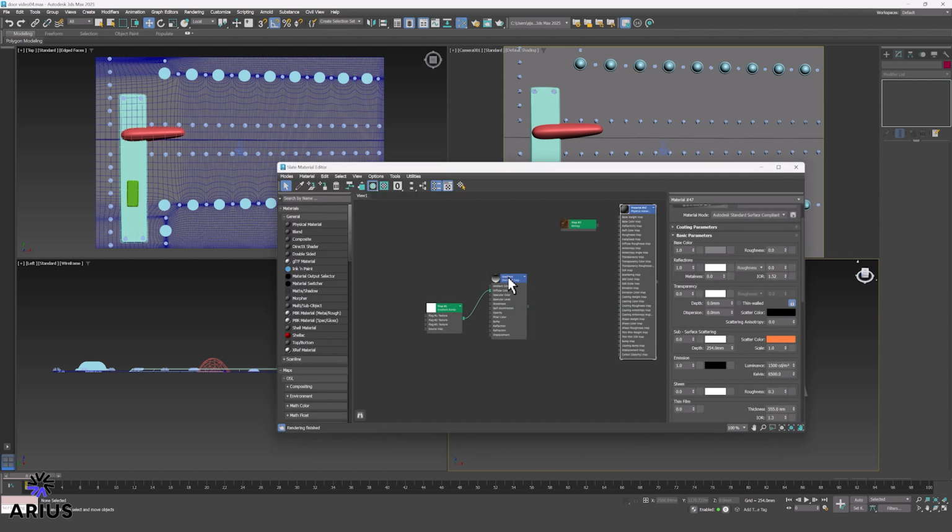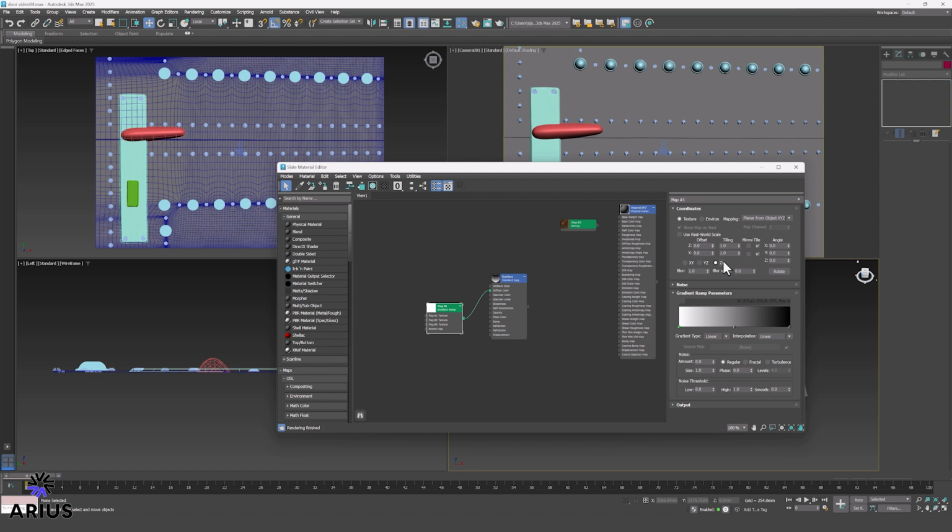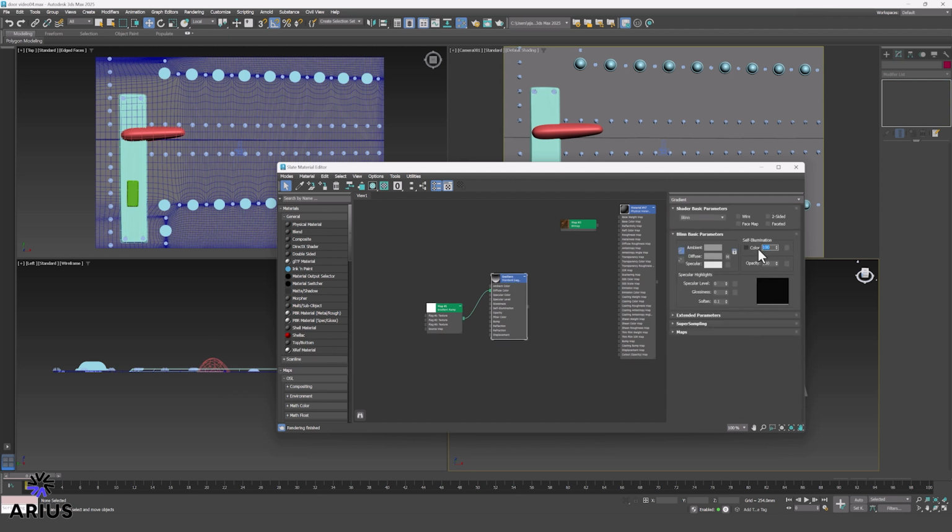To make the elevation tones, create a standard shader with a linear black to white gradient ramp, using object XYZ coordinates aligned with the model's vertical axis. This will place black at the highest point and white at the lowest. And ensure the shader is set to self-illumination.